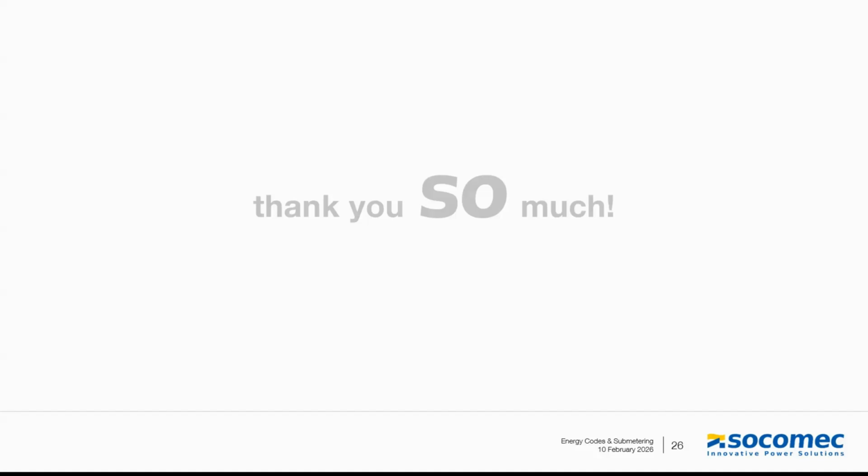Do you address power quality issues or mitigations? Some of the power quality meters that Socomec offers do monitor power quality. We're able to set up alarms based on thresholds, and we can record sags, swells, and interruptions. We're not an active device. We're monitoring and reporting those issues.